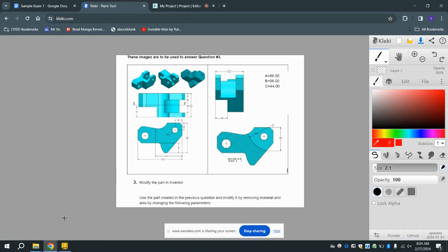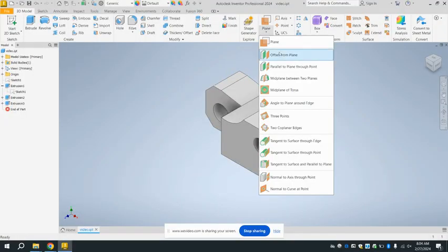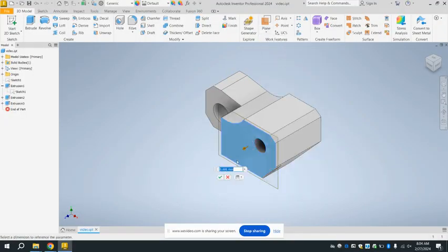Okay, so we see this is 12 and then 24, right? So, and here's C. So what we could do is divide C by 2 because this is right in the middle. So we can make a plane 22 inwards, offset from the plane from here, and then we're going to do negative, so it goes backwards. Negative 22 right there, and that should be right in the middle.